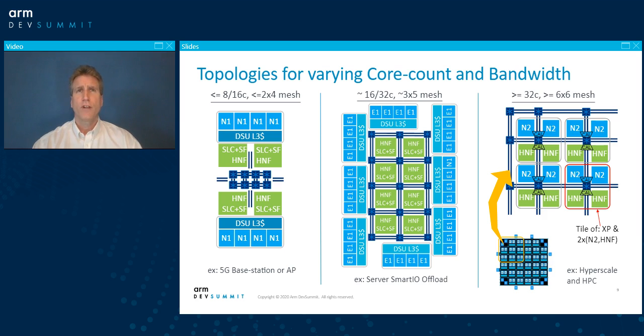And lastly, for very large configurations and higher core count, we advise placing the CPUs and home nodes within the mesh in a tile configuration to allow for higher core count and easier chip layout. These CPU home node tile templates can then be replicated with parameterized signals per XY location. Memory and I/O should still be symmetric around the configuration and around the mesh to provide good balance and distribution of cache, memory, request, and response time to minimize congestion hotspots.